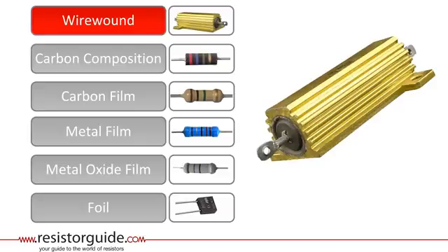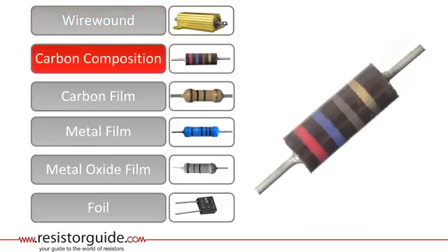They can have very low resistance values and can be produced fairly accurate. Furthermore, they are very durable. A disadvantage is the parasitic reactance for higher frequencies. Carbon composition resistors are constructed with a mixture of a non-conducting ceramic and fine carbon particles. They are also very old and used to be the most common resistor type a few decades ago. Although their properties are inferior to other types, regarding for example tolerance, they are still in demand for certain applications. For example, they have the ability to withstand high energy pulses.